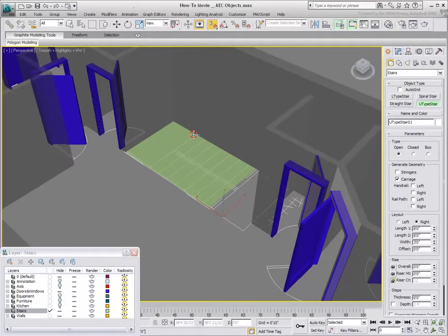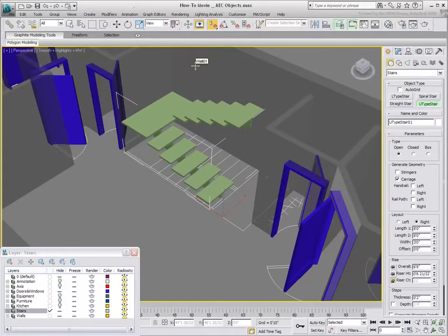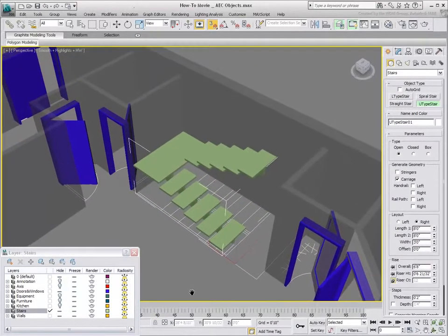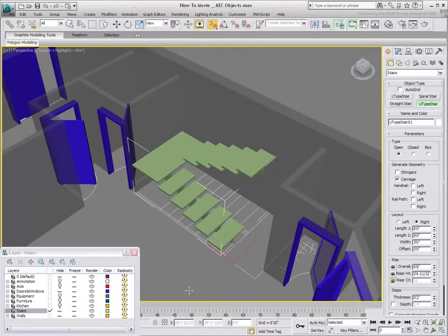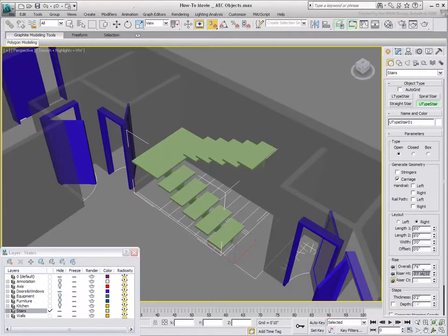You can then define the overall width of the stairs and ultimately the height. As with those in Windows, the length and width of the stairs were drawn using CAD reference and snap tools. You must now define the overall height and number of steps. In the rise group, you can define a riser height of 7.5 inches and lock that value.